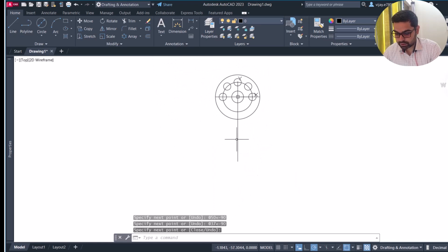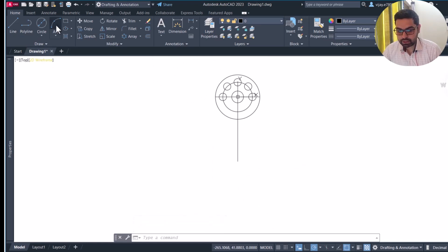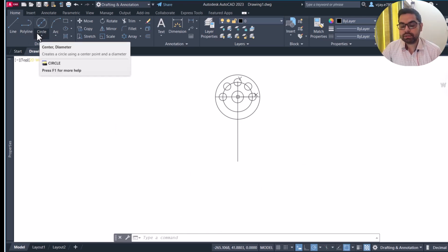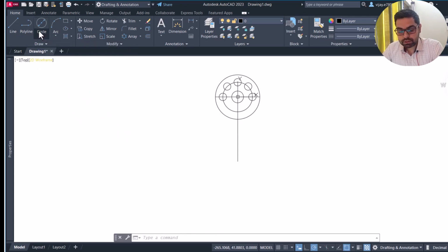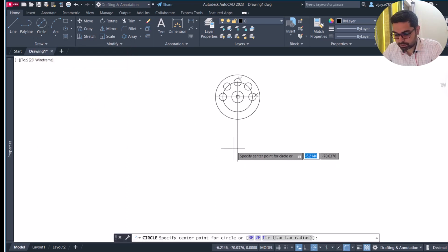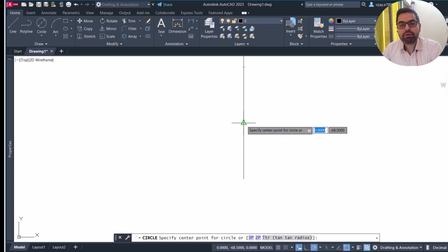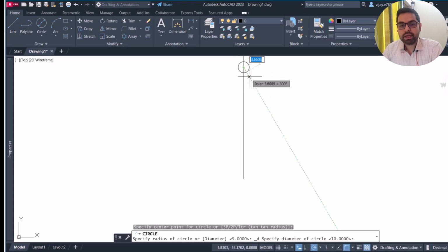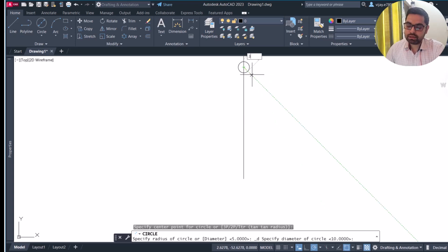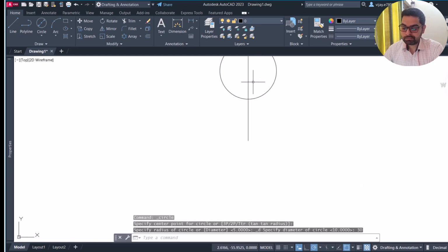Now after that, what I'm going to do is on this 50 segment, basically I'll be drawing an arc. I can draw an arc of 30 radius, or I can use another way, that is using center diameter and specifying this point. Just take a look. This point that we are seeing here, this is the midpoint of the 37 line because we are seeing a triangle here. But take a look at this one. This is a square. So this is the end point of one line. So this is the identification, 30 and enter.